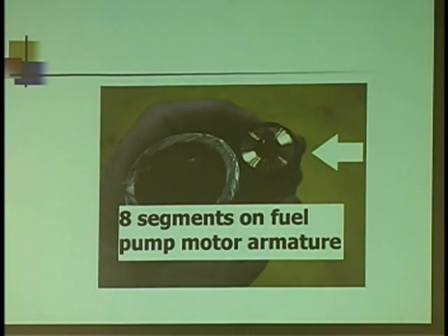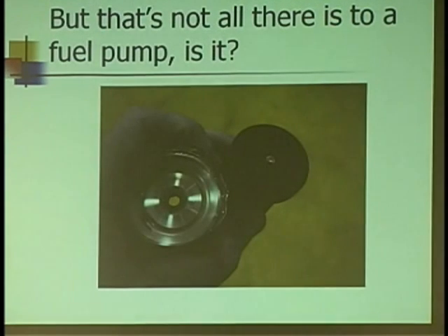And we spoke briefly about this before, but let me hit this again. In a motor, what impacts the current draw? Not just the electrical, but the mechanical, the load. That's on this end of the pump. Is it possible for you to have a full tank of gas, but a fuel pump that's dry? Sure. Aren't they in a well? If the inlet screen is clogged shut, I can have all the gas in the tank I want. It'll quickly suck that well dry.